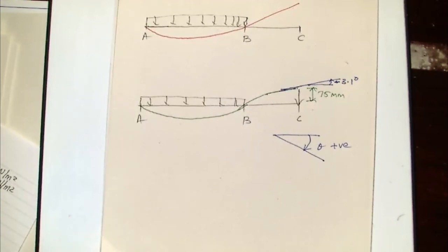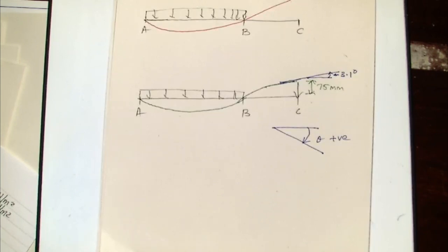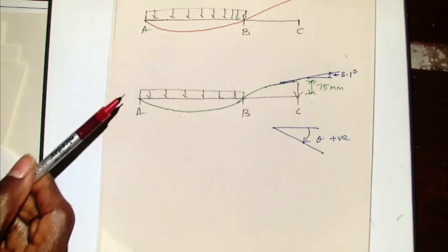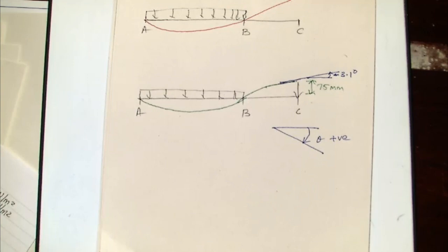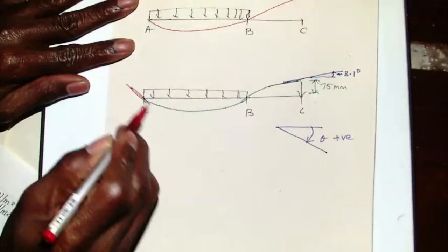And about the boundaries, can we choose different boundaries as well? If we know that when deflection equals 0, the angle will also equal 0, can we set this? No, not at the support. For example, if you look at that here, the deflection is 0, but the slope there is not 0. If I draw a tangent to this, right there, I'm not going to get 0.